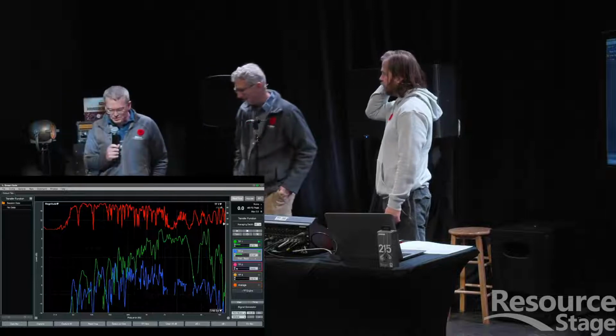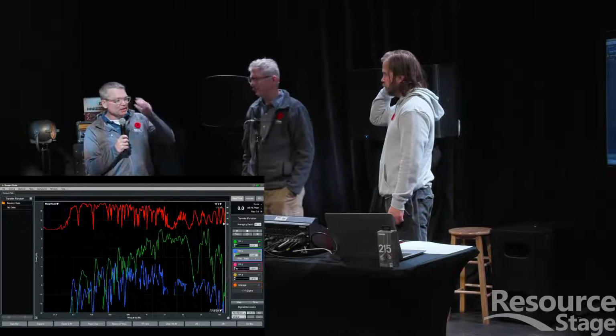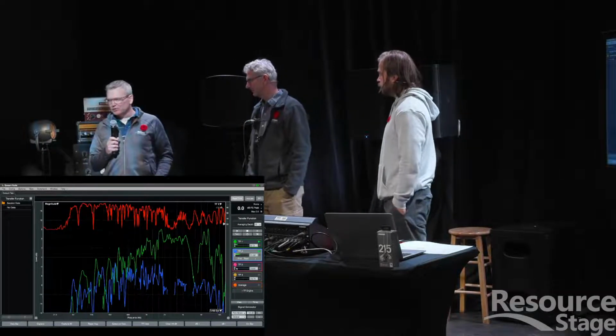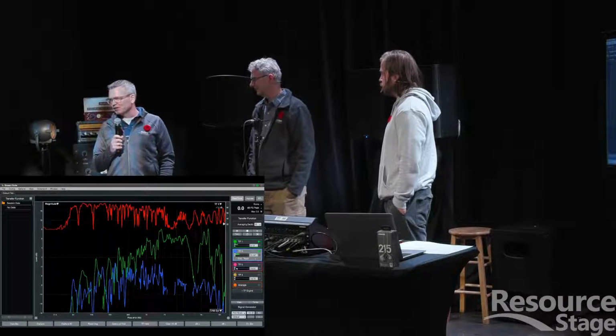So, in a number of the things that you guys have talked about tonight, we have had phone calls from customers, and they'll call us out and say there's something wrong with our speaker system, or there's something wrong with our microphones. We need to replace our microphones. And you can tell that that polarity flip that was done on the console can be just two wires mixed up on the cable, right?